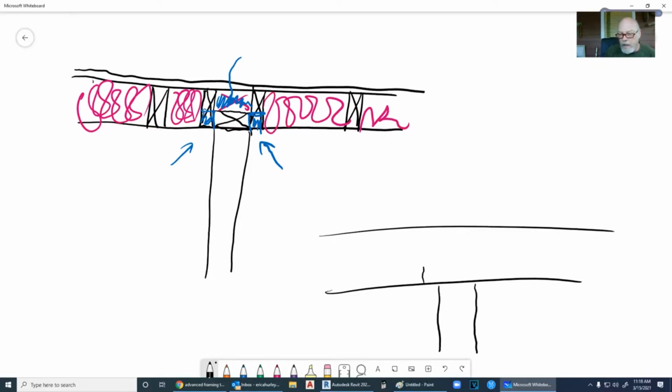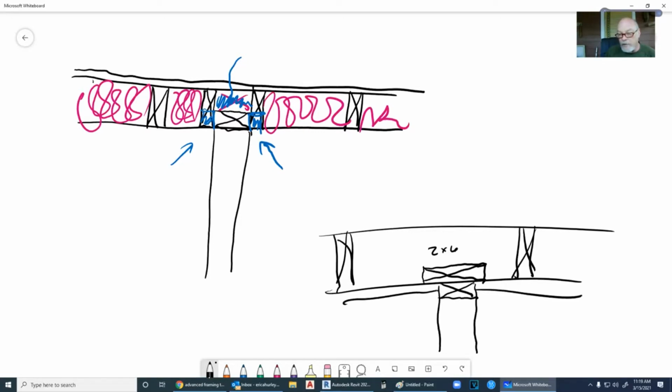Actually, one way, if we're using a 2x4 wall on the inside, so we've got our own center spacing studs through here, and they don't matter where they go. We can take a larger 2x, so this is a 2x4 wall, and we can put a 2x6 in here sideways that's attached top and bottom, and then we have something that we can attach our stud for our intersecting wall here, and then we still have room that we can put drywall to it, and we can insulate all the way through it.